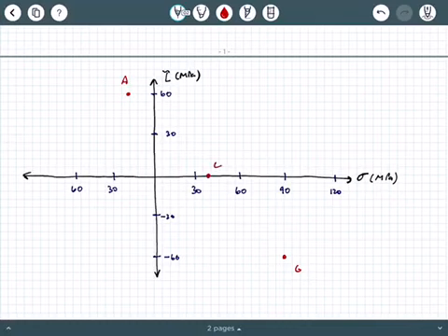And remember, as we've mentioned in all of our previous videos on this topic, AG is a diametric line. So AG defines a diameter of the circle. We already know where the center is. That's 35 comma 0. So if we want to put the 35 comma 0 in, that's probably going to be right about here. On your homework again, you should draw this to scale.